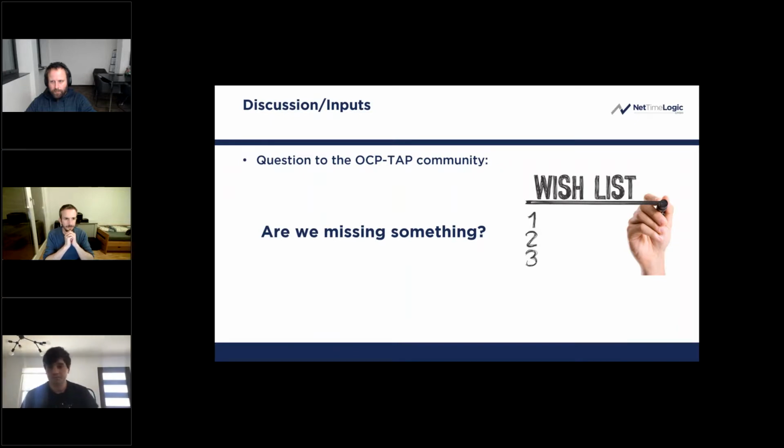You're welcome. We also have a parallel effort, looking into alternatives, or what we can do in general with a GNSS receiver, what we can do with a high stability oscillator. Right now, the atomic clock is almost a must based on the design we have, but that's not really true. We can easily go to an OCXO or other things.